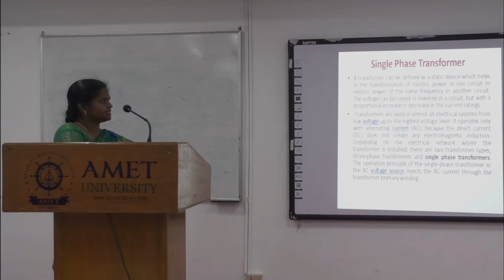A transformer is a static device which helps to transform electric power from one circuit to another circuit with the same frequency. The voltage can be raised or lowered in a circuit, but with a proportional increase or decrease in the current ratings. Transformers are used in almost all electrical systems, from low voltage up to the highest voltage levels. It operates only with alternating current, because if a direct current is given, then there won't be any electromagnetic induction.